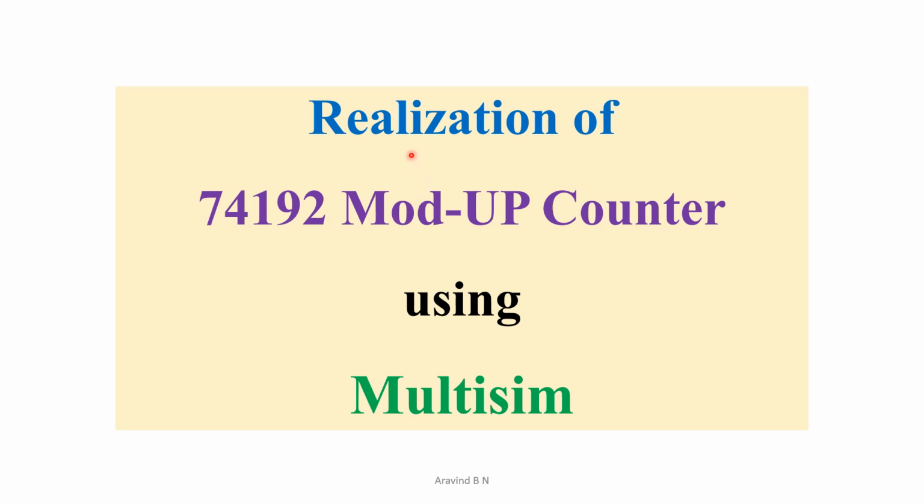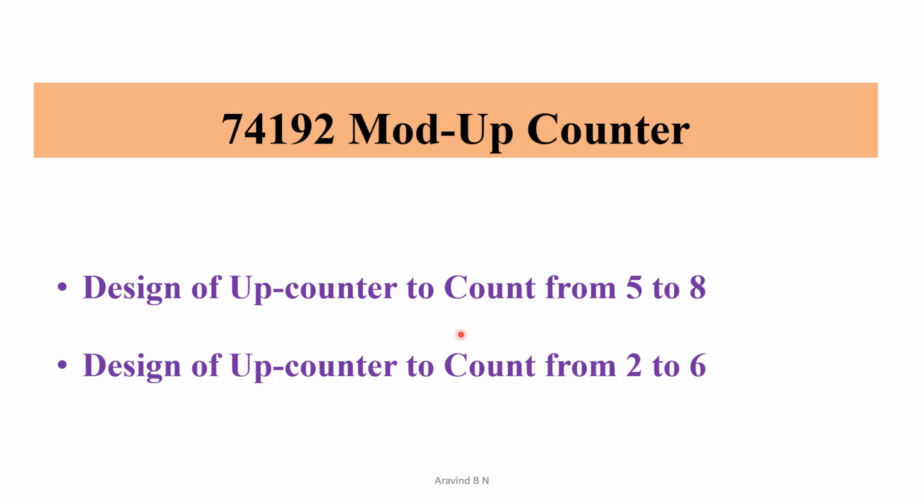In this lecture, we are going to realize 74192 mod up counter using Multisim. Two different mod counters are being realized over here. First one, design of up counter to count from 5 to 8. Second one, design of up counter to count from 2 to 6.